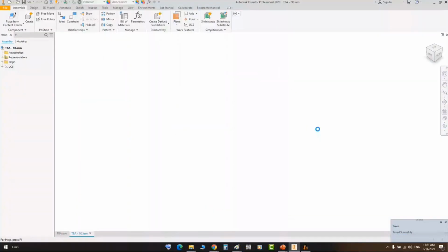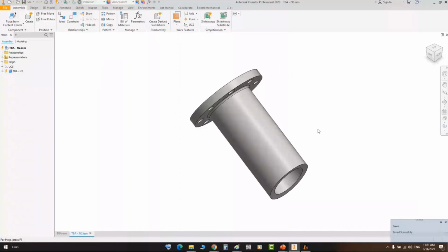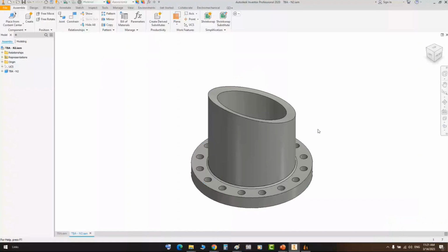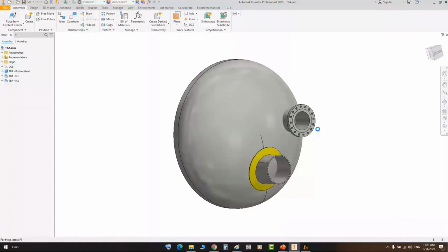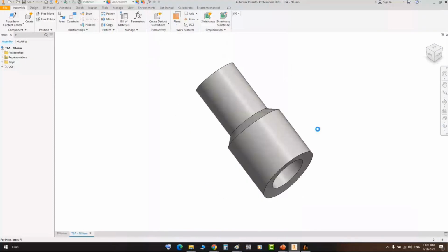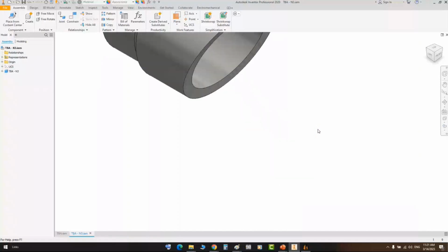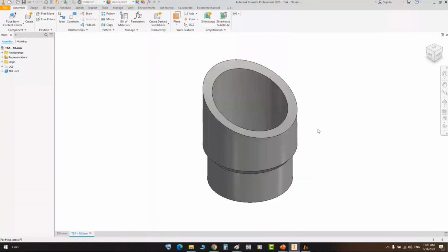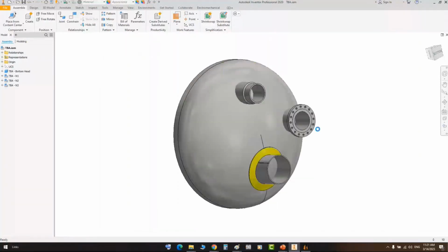we will get 4 nozzles at the bottom. One of them is a nozzle from blade, then a long weld neck nozzle, then a forged hub nozzle, and the last one a forged hub with lips, and the insert bed of this lip with a different thickness than the head thickness.